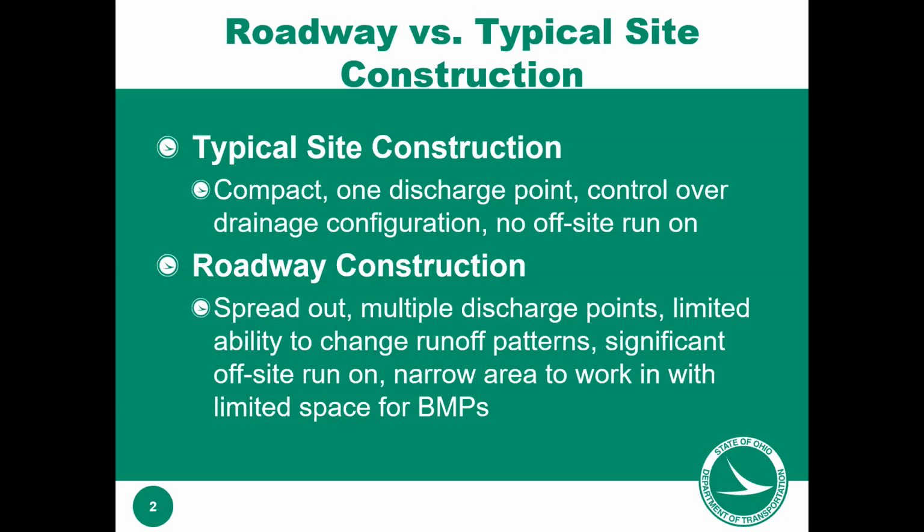There's multiple different discharge points. You have limited ability to change runoff patterns because you might have something coming in that's going right back off under or across the road. There's a lot of times offsite runoff. You have a narrow area to work with and limited space for BMPs.